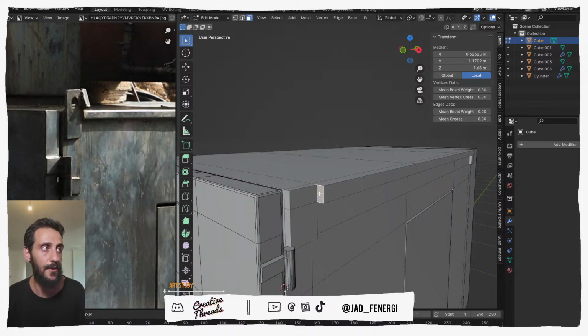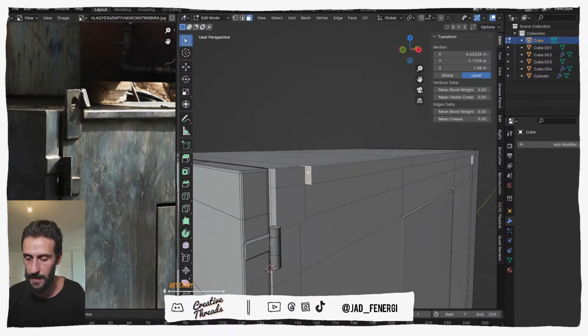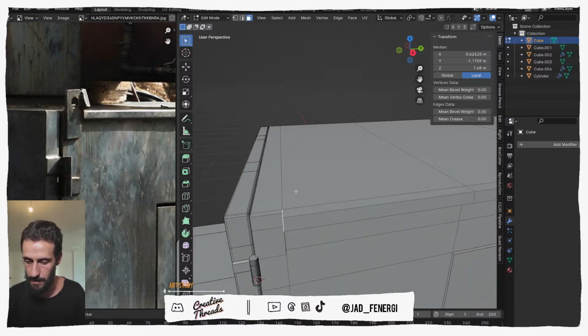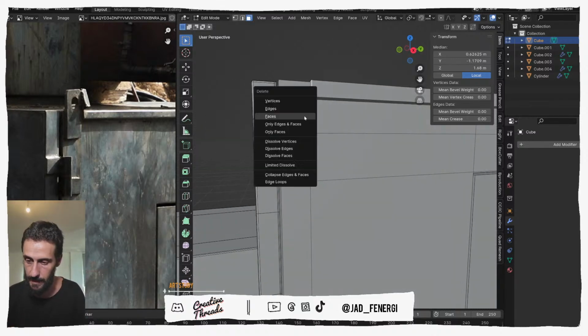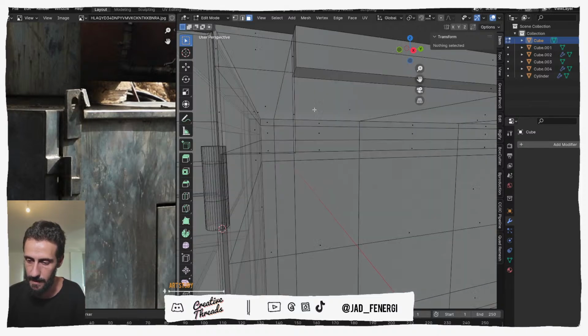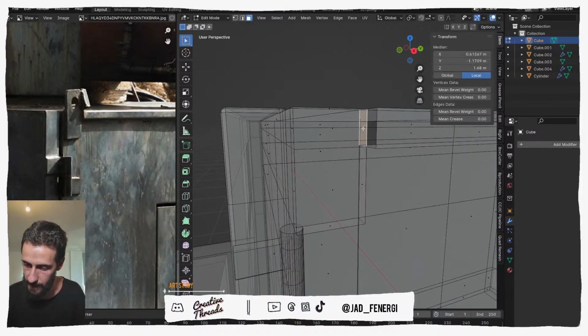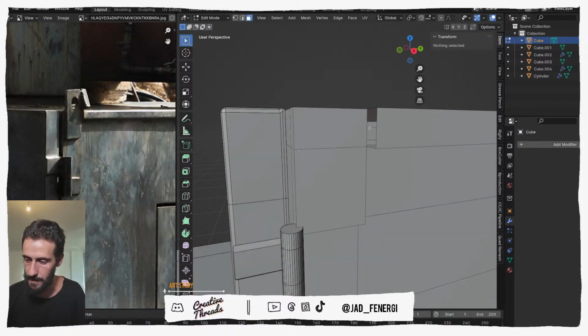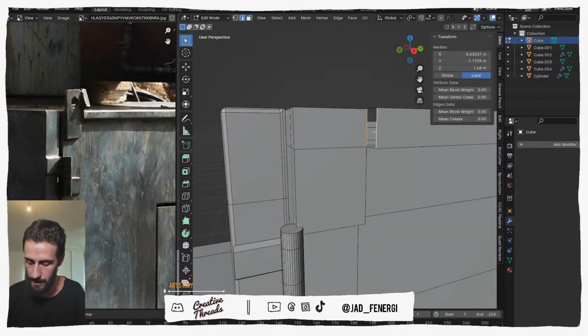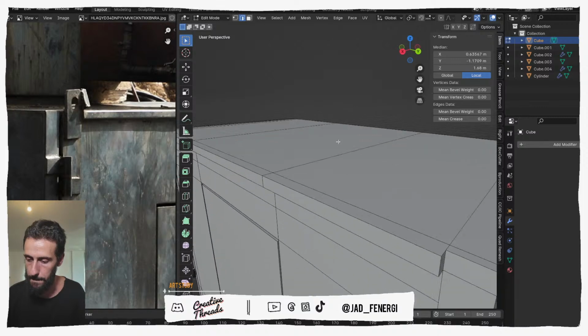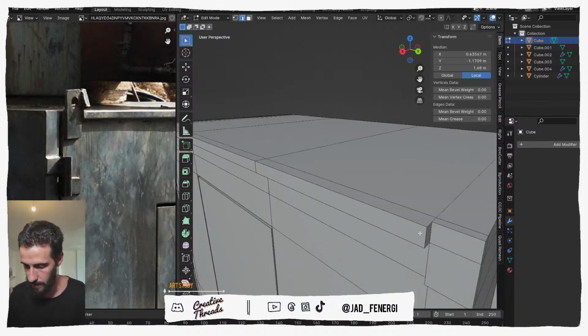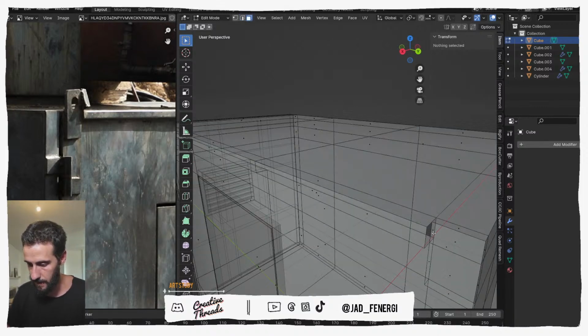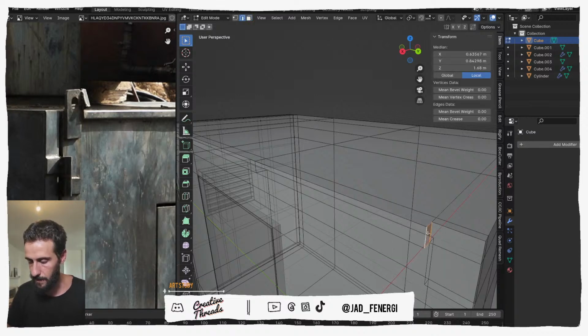Now, in terms of clean model, we now have 2 faces here and inside of here that are overlapping. You can clean that up, that's not a big deal. So we can delete this face, press Alt Z, you have a face in here, you can delete this face, and now you can select these 2 edges and just press F to fill them. You can do the same thing here. So 3, delete this face and delete this face, then press 2 and fill these 2 faces.